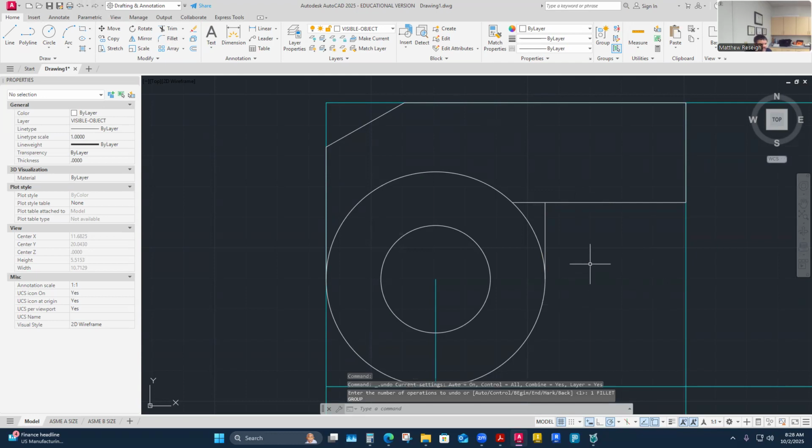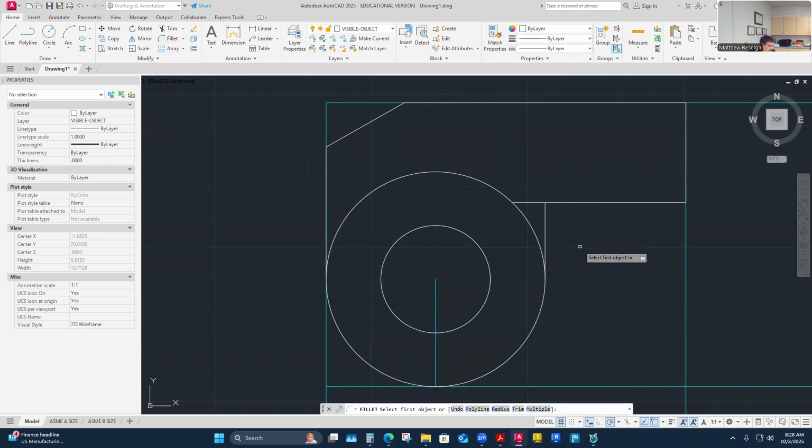Oh no, I know. It didn't load my, that's weird. I thought it would load my last 1/2 inch. It didn't do anything. Let me do my radius again. I thought it always preloaded my last one. Oh, I undid the command. Sorry, that's why. Since I undid the command, it had nothing preloaded. So now I had to re-enter 1/2 inch. Oh, that looks so much better. I forgot, I Control Z'd so it didn't have any data input for the radius. So now anytime I pick fillet, it will have 1/2 inch loaded.